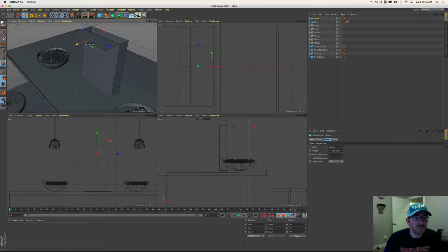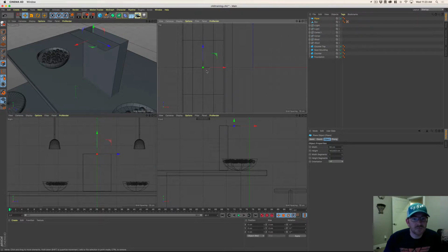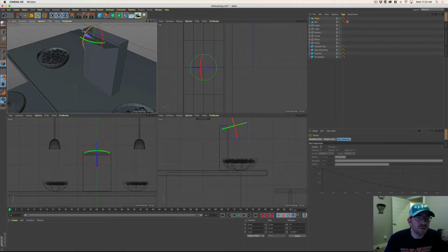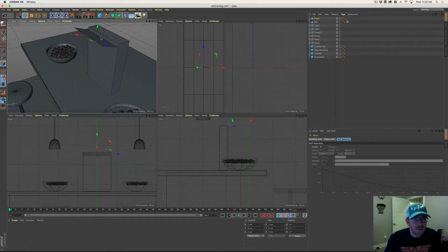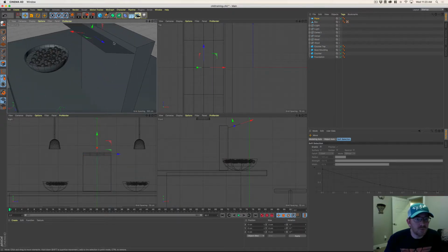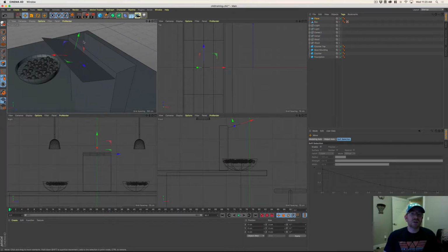All right, so we're going to position this so it's touching the edge. I also maybe want it to open up a little bit, so I'm going to use my rotation tool and just kind of rotate that up right there. You know, I'll need to pull this up. Here's one thing that's really helpful, and I'm going to use this right now. These coordinates, once you rotate something, the coordinates in the plane get really messed up for this object.